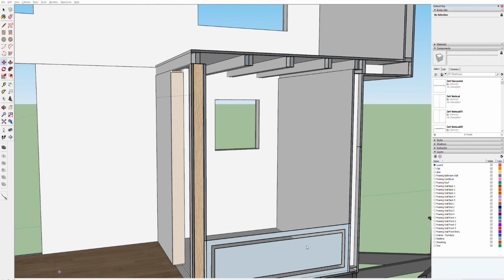Alright, so now our new dimensions are 8 and 9/16 for the first riser, 9 and 5/16 for the remaining risers, and 7.5 inch width tread. Alright, let me give that a shot and see what that actually...